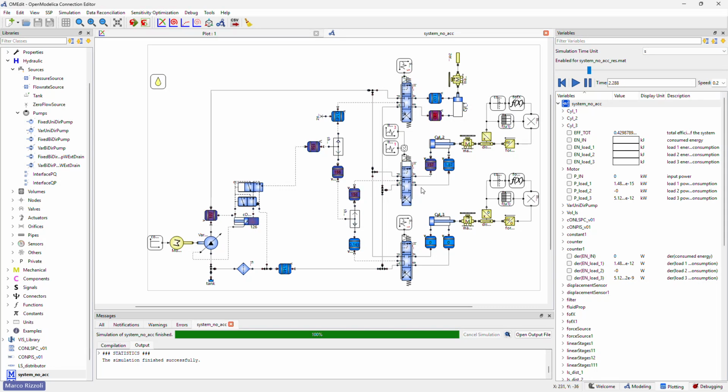Then we move to the second movement here. We are partializing the opening of the distributor since we want a speed control of this cylinder. You can look at the displacement of the pump that is regulating its displacement. Thanks to, I go back a while, thanks to the flow compensator that is regulating the pressure at the actuator of the displacement. Then I will push the distributor to the side to have the final movement at full speed with full displacement. And this is the second movement that we are evaluating in the cycle.